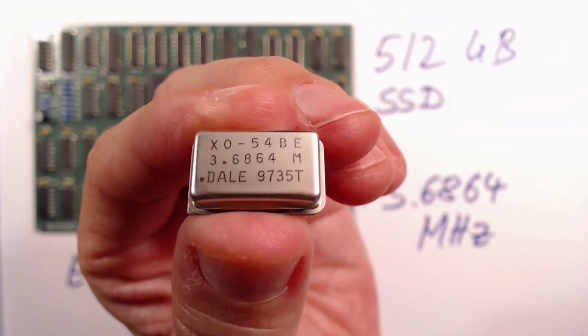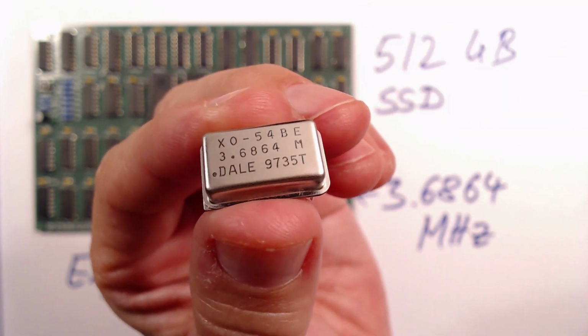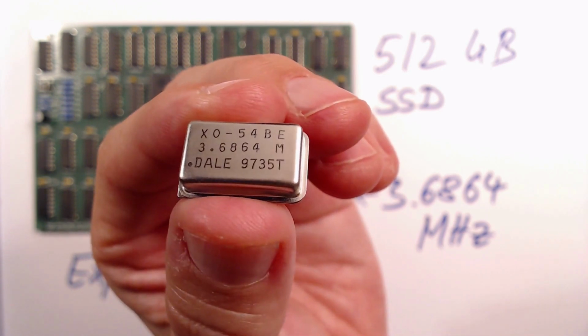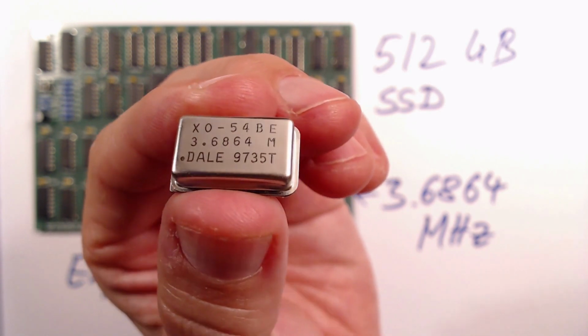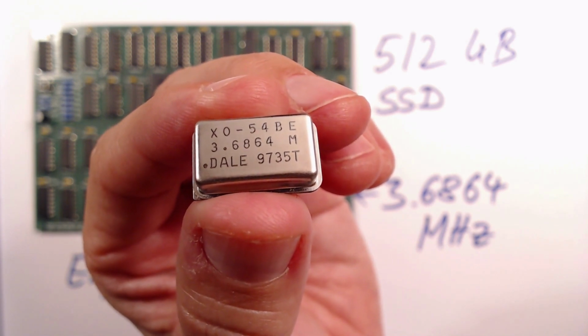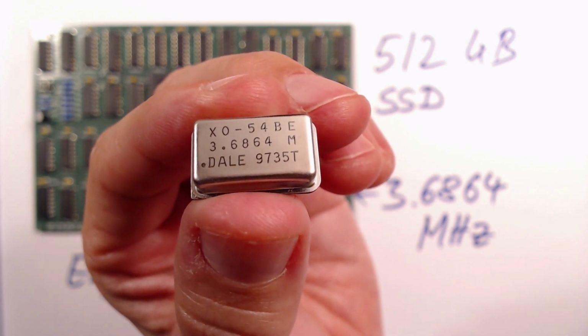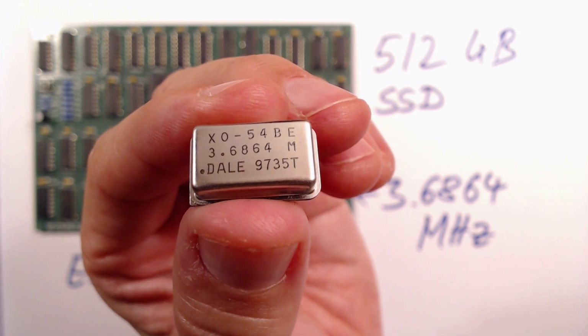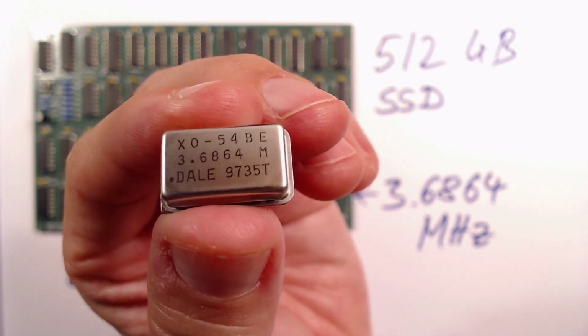I've managed to double the clock speed of the CPU, but I will spare you the details here. It's now running comfortably at 3.6864 MHz, executing approximately 0.5 mega instructions per second. That's about the processing power of a C64 or Apple II.